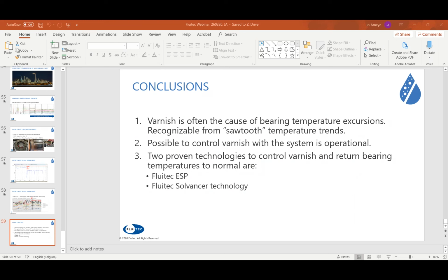Cooling? It will not help. Cooling will only agglomerate more, and the solubility goes down, and if solubility goes down, you will have more deposits of formed insolubles, and then more layers of varnish. Think about your hydraulic valves, regulating valves. If you cool them down and you have varnish contamination, they will be sticking just because you've cooled down the oil. So it's not a solution. Absolutely not.